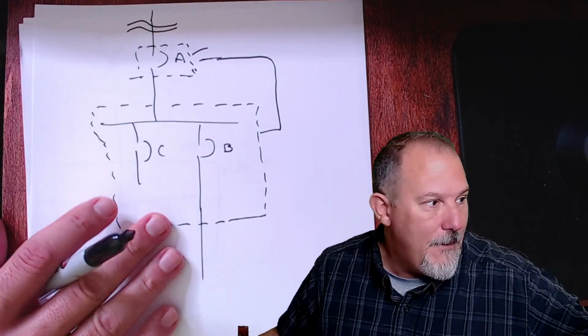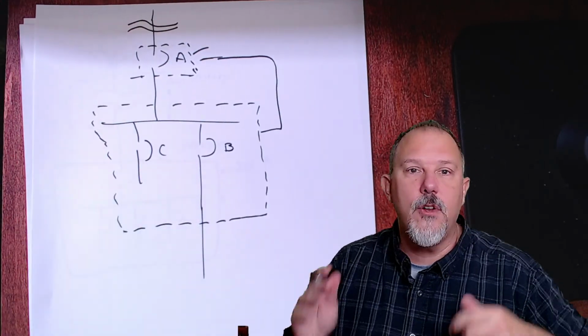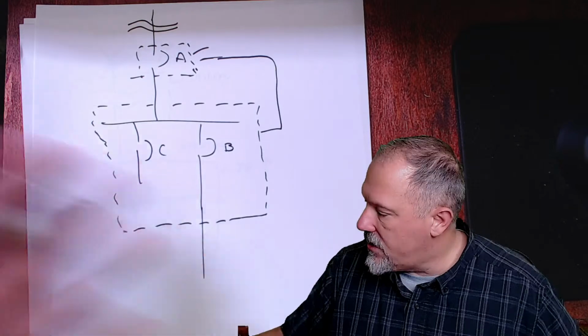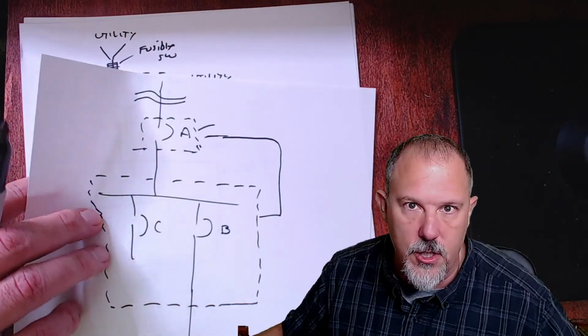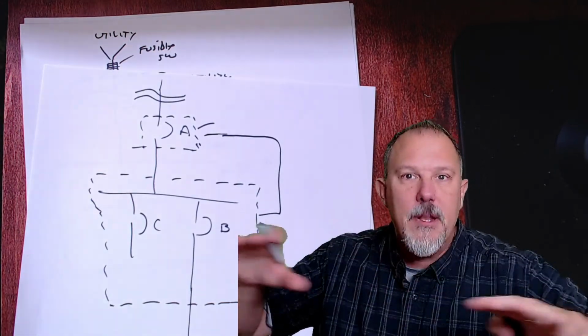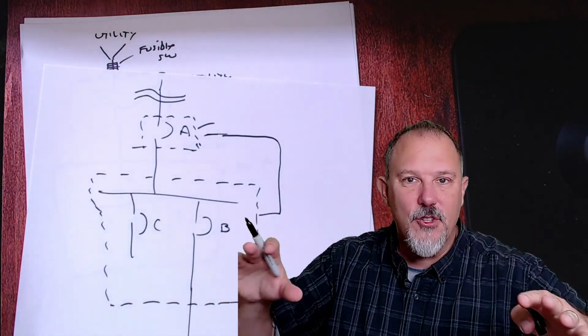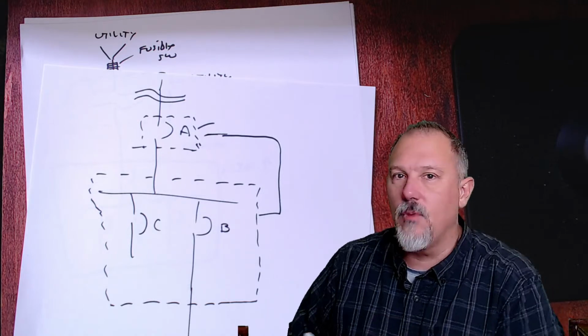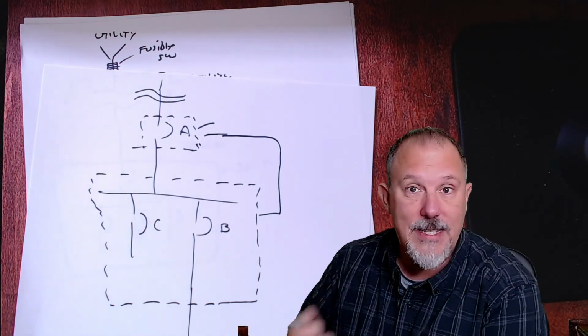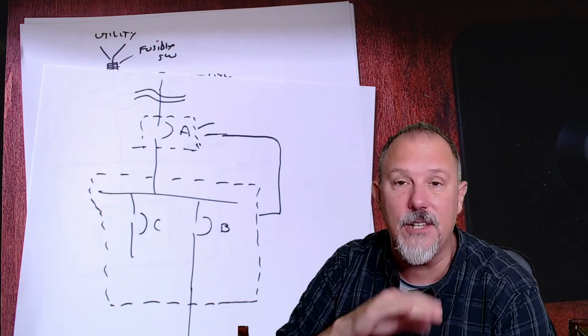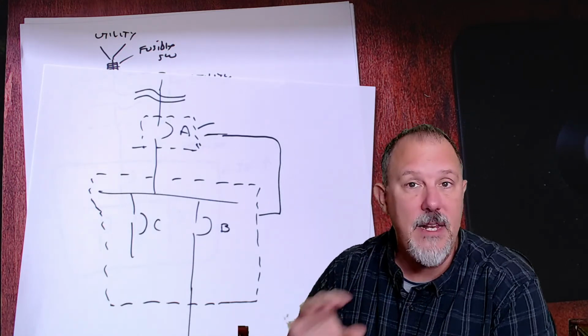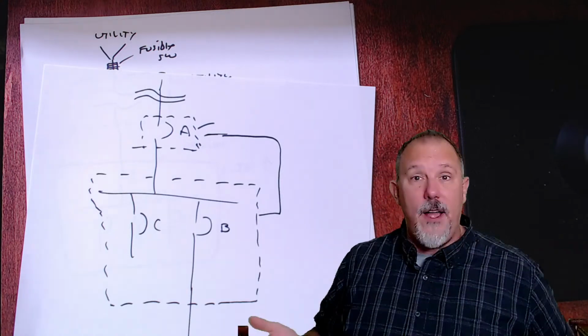Now, what Summit is saying is, even on the medium voltage side, now this is on the low voltage side, but on the medium voltage side, I'm going to have a medium voltage distribution, and I can apply arc reduction technologies at medium voltage. Right now, the National Electrical Code has requirements, like in 240.87, which we mentioned earlier, but that only applies to 1,000 volts or less. It doesn't apply to medium voltage applications. And the question is, why not?